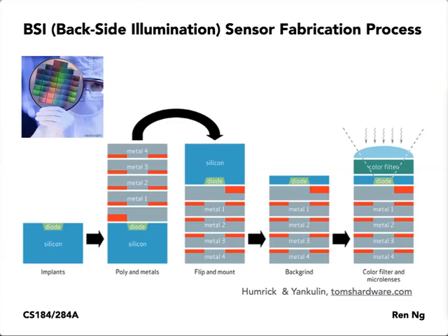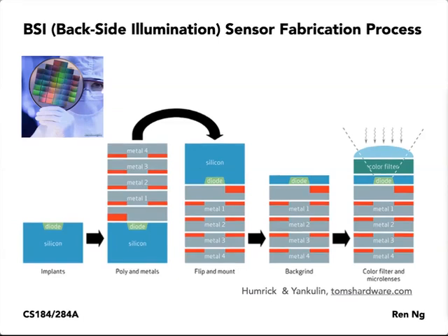But now, once you've flipped it over, what's happened? The metal layers are underneath the photodiode. The problem is the original wafer is still on top. The wafer is quite thick, many hundreds of microns thick. So then you can grind it down. Using mechanical processes, the silicon wafer is actually abraded, sandpapered down, if you will, glorified sandpaper, until the distance that's remaining of silicon before the photodiode is tiny, like a few microns.